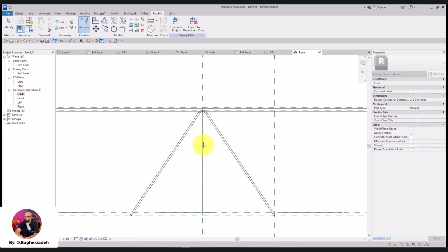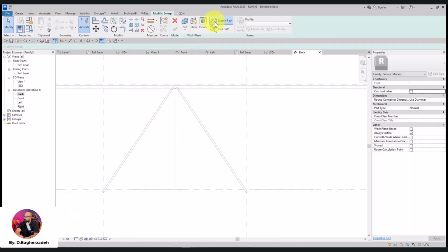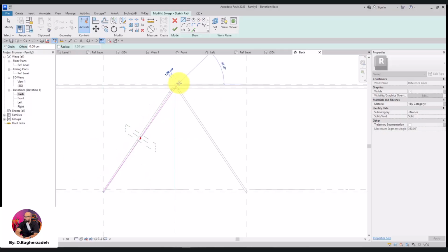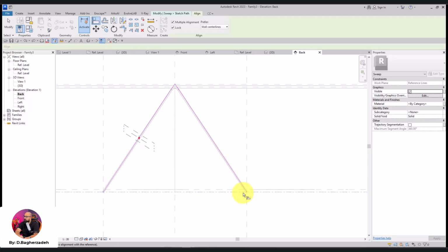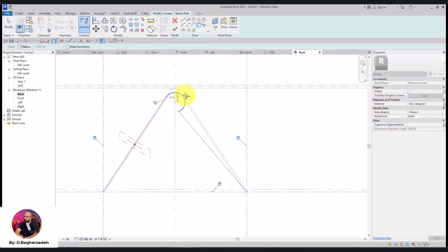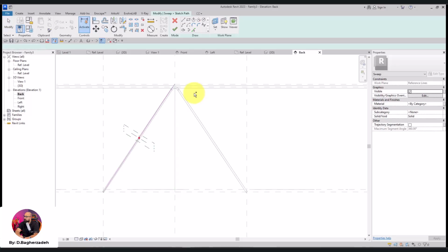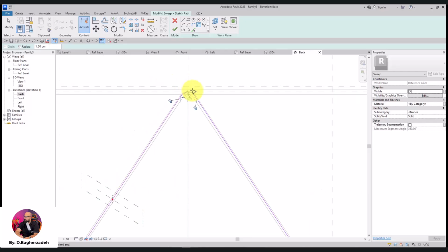Then I want to open back and then repeating the same process for the other side of the project this way. I specify the first and the second points. Before aligning it, I check radius, adding fillet. But if we do not check radius and lock the endpoints of the line, let me show you the results. Then if I want to add the fillets, after locking the points, we'll have abnormal results. So please add the fillets before aligning the endpoints.